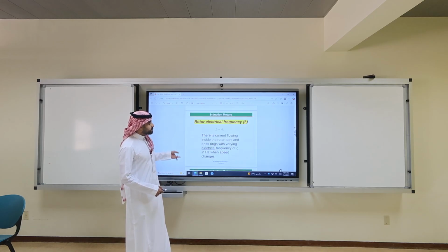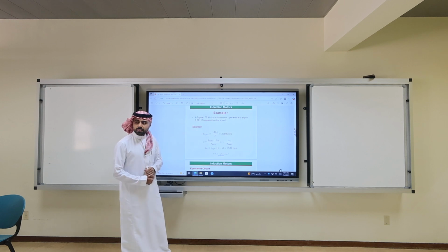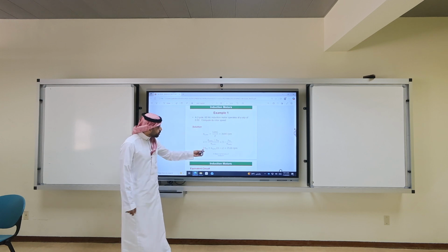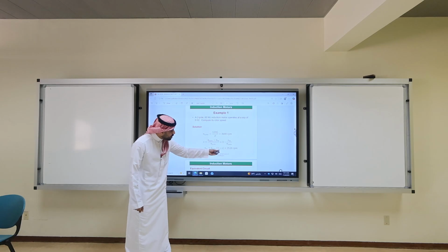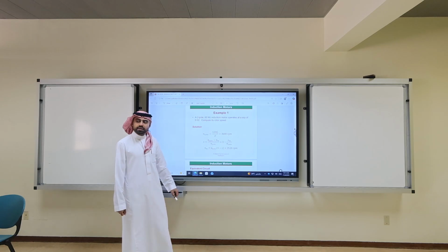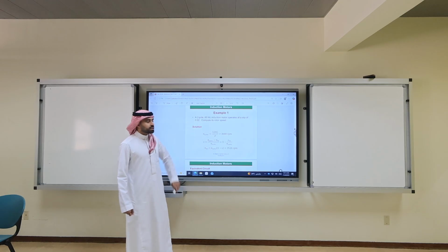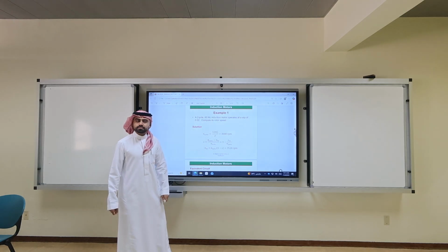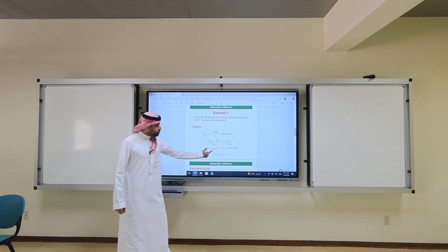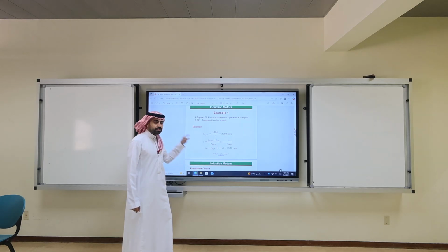And last lecture we did this example. Do you remember this example? Yes. Where we calculated nm from n sync, which is 1 minus slip times n sync, which is 3528 for a 2% slip. So the more slip, the slower nm.